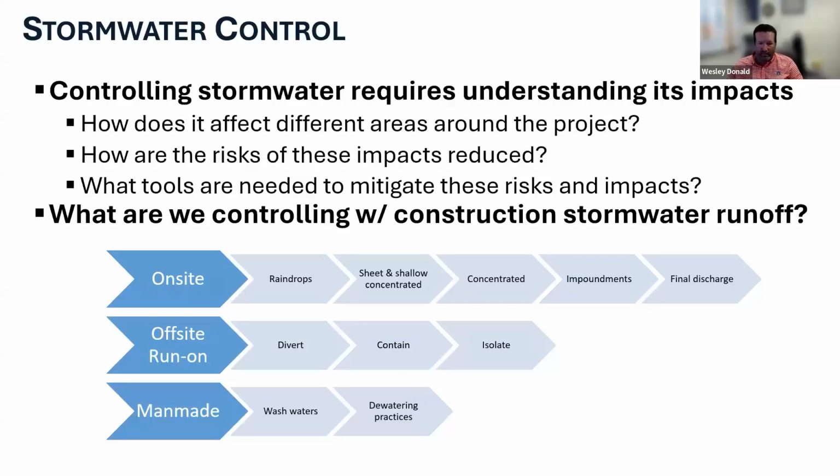And then there are times where we have man-made runoff that we have to deal with. So wash waters coming from vehicle washing, or when we wash tires and things like that, we've got to manage that and control it. We can't let that discharge. Dewatering practices: if we run into a water table that we have to dewater so we can get in there and work, well, where's that water going? We've got to manage it. And those are also very well controlled.